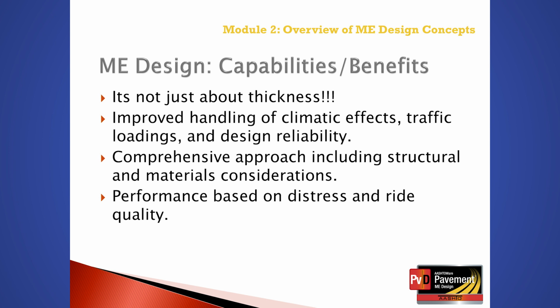Many design features should be considered in determining an appropriate design strategy. Some examples for flexible pavements include determining the asphalt binder type for different climates and traffic conditions, asphalt mixture properties, both volumetric and mechanical, and how those properties can change over time, the bond between adjacent layers, and drainage considerations